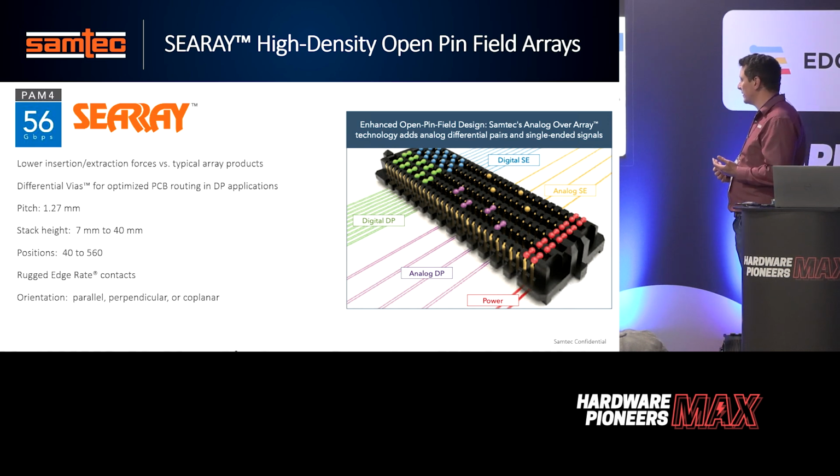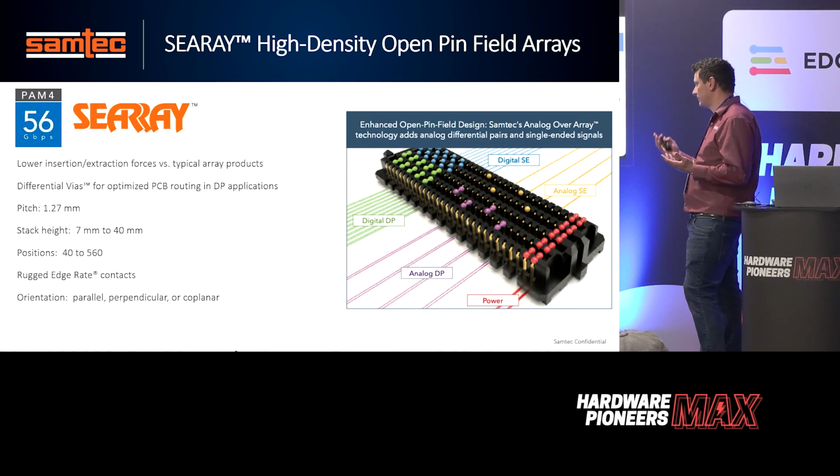So it's a really rugged connection with high mating surface. It is made of beryllium copper, so it can withstand vibration really well. We can actually pass environmental requirements similar to military type standard, MIL 810, for example, and is nowadays even used into space applications.